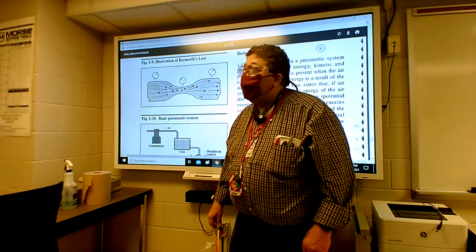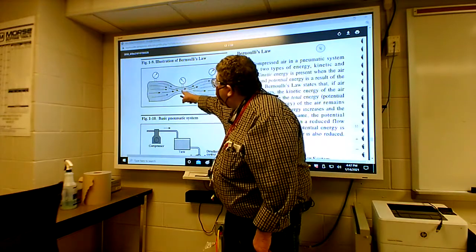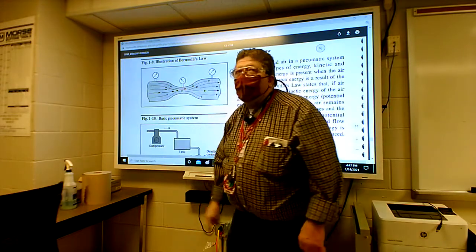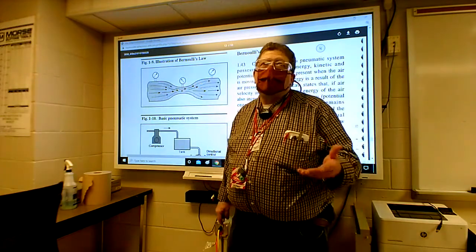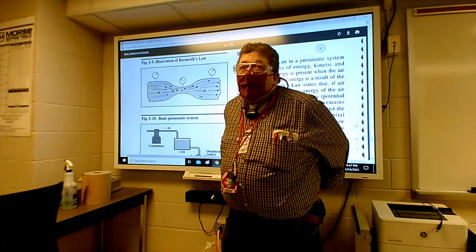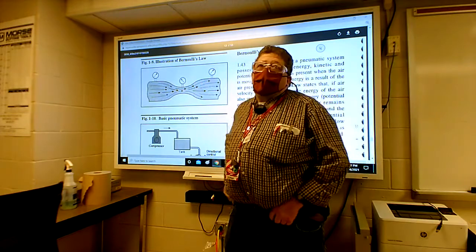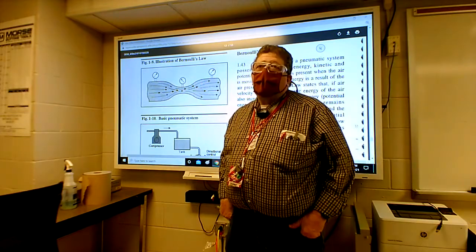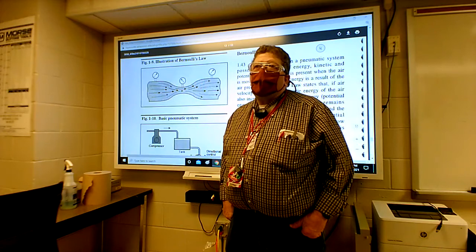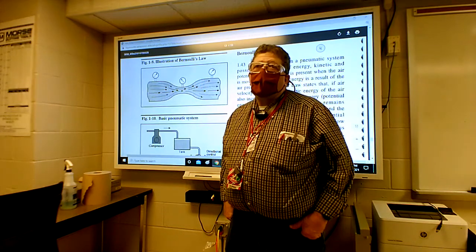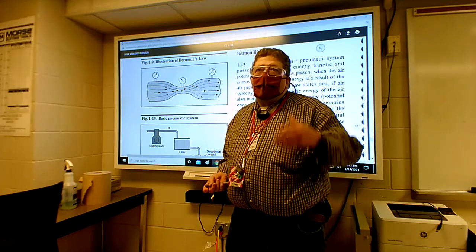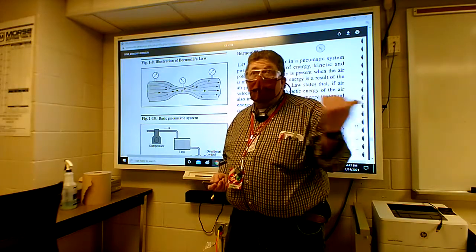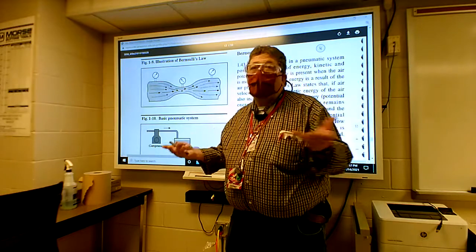Technically, if you do it with a pressure gauge in there, the PSI goes down, but it's going faster, so you think it's more pressure, but it's not PSI, it's actually speed that goes up. Your velocity goes up, but your actual PSI goes down. So we think it's pressure, but it's actually velocity that goes up, because it has the appearance of being more pressure.